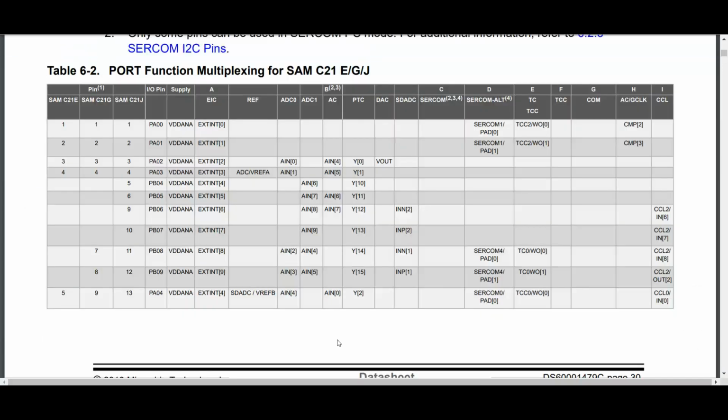The real solution to the entire headache is for me to start using the included analog to digital converter number 1. It is a completely separately configured analog to digital converter, which is great. I'll use ADC 0 in single-ended mode to read current, referenced to I/O ground, and I'll set up ADC 1 as differential and read between the two pins that come from the resistor network. And that's great. So let's scroll down ADC 1's pin definitions and see what we can see.